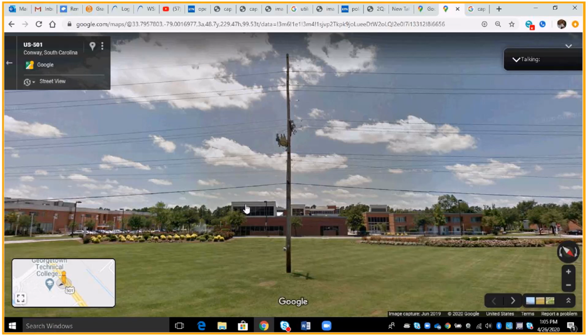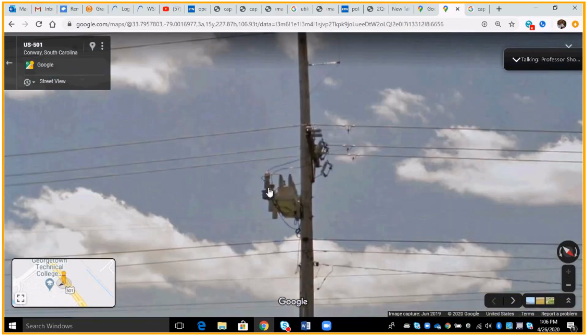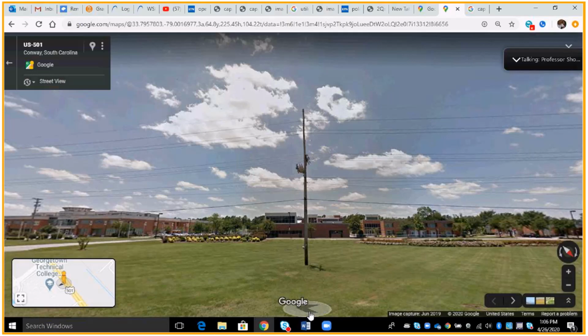So when the motors start up in the college and I have a lot of inductive load, SCADA will send a signal to this radio. This radio will send a signal to the bank, and the vacuum switches, which are motorized, get the signal and open and close as needed. The switches do not. That's just an isolation method in case you have to work on them. And we'll get into that further.